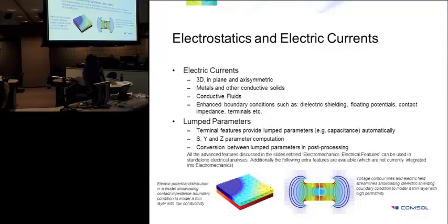The two figures here at the bottom of the slide show two particular boundary conditions in these interfaces that allow you to model a very thin conductive layer and a very thin dielectric layer with very high permittivity. These boundary conditions allow you to not specifically model the thickness because they're very thin. If you model the thickness, you will have problems with meshing the very thin elements and then a lot of mesh elements and increased computational time. Instead, any thin layer can be modeled with specific boundary conditions. And it almost exists for any physics, not just this particular physics.